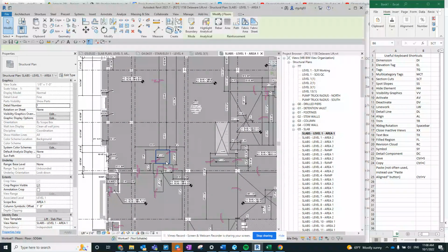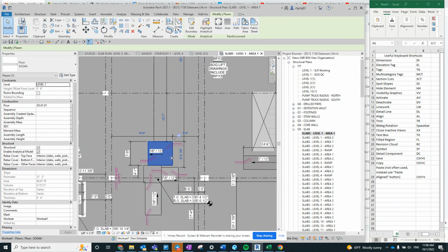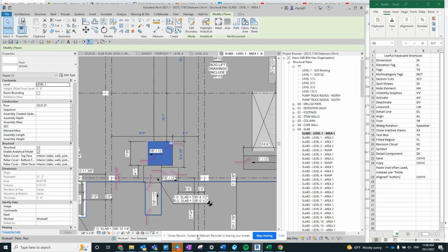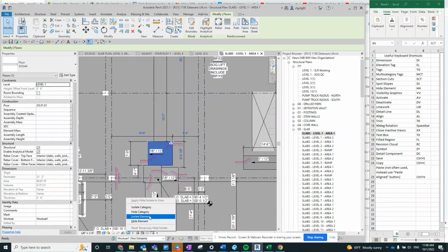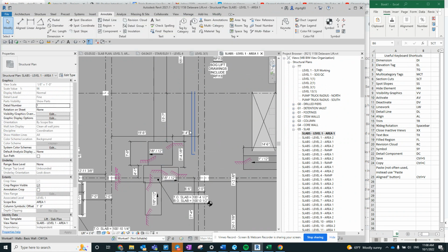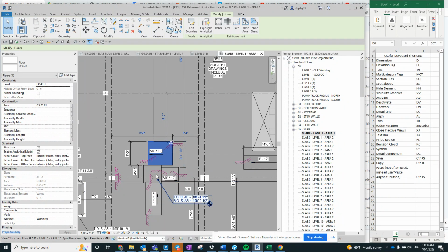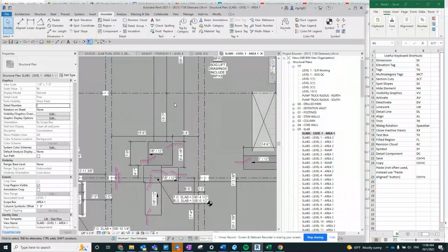If you want to hide an element, you can click on that element, and I set it up as HH. The standard setup is that HH does a temporary hide element, but I don't prefer to use that, and so instead I use this as hiding an actual element.